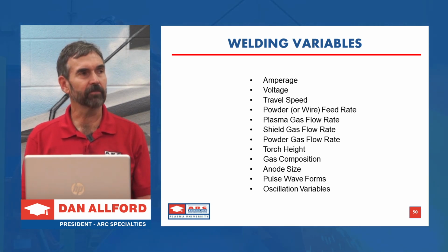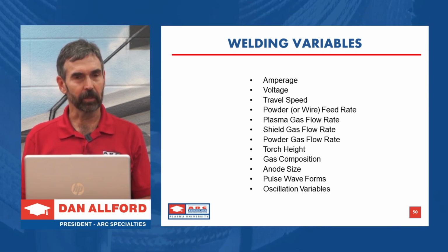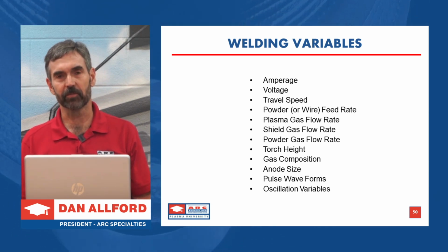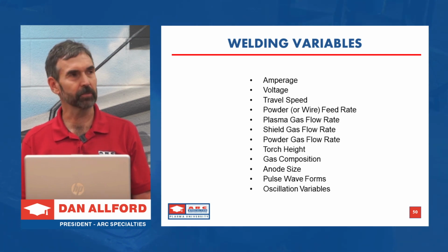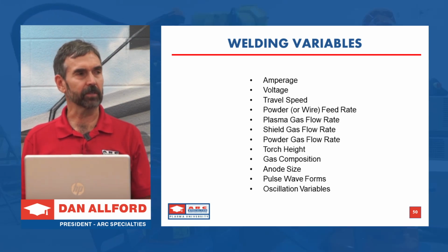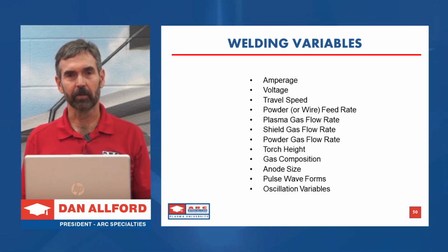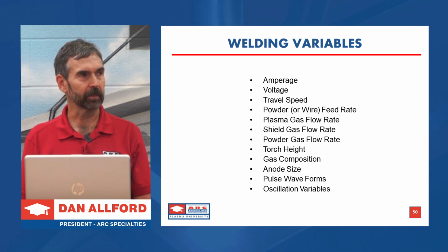After you understand each of these variables and learn to optimize them, frequently you seldom move any of these variables after you initially optimize them. You just make a few changes in amperage and powder feed rate. So it's not quite as daunting as you might suspect. Amperage is pretty much the heat input of your part. The more amps, the more power you're putting in the part.